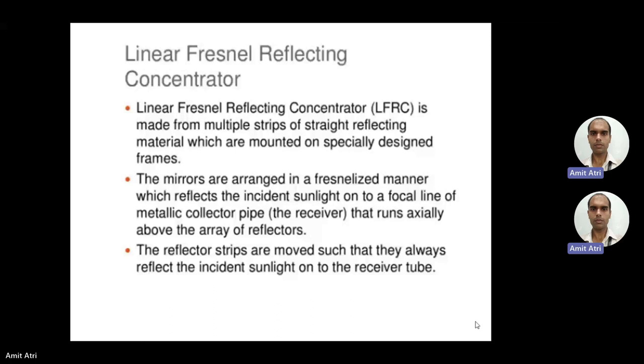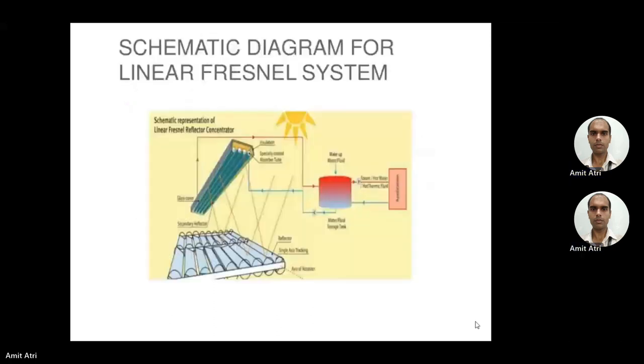Okay, these strips are reflecting through this. On the base, the sunlight is falling, and it is reflecting back upward. So that is the absorber. Glass cover, then tubes are there, through which the fluid, the water or the fluid for collecting the heat, is circulated. Okay, so the light is falling first on the reflector on the ground, then reflected back to the surface of the absorber. Absorber tubes are right there on the above level. So this is how it is working.